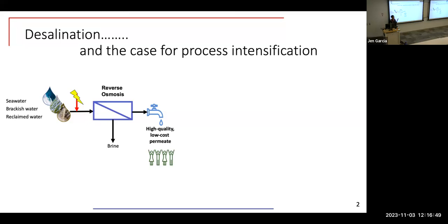The problem is with these types of separation processes, and really any sort of treatment process, you have a byproduct. And in this case, this byproduct is a concentrated brine. Okay, so as we concentrate this water, depending on our source water, the higher the salinity, the less water we can recover, because it just becomes not economical anymore. We can recover 50 to say 80% of the water that's coming into these processes, which leaves about 20 to 50% of the water left as a brine solution.